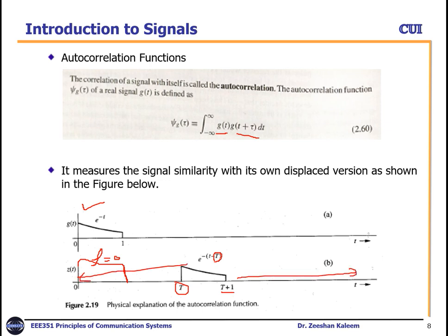So wherever we have more correlation, meaning a more positive or high result, it means that the signal is present. If by moving here and there we still don't get any value, then it means that no signal or no target was present. So this was the concept of using correlation functions and one of the applications in radar. And similarly, you can use this in a number of applications.